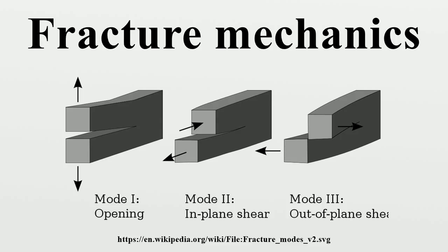The energy release rate for crack growth, or strain energy release rate, may then be calculated as the change in elastic strain energy per unit area of crack growth, where U is the elastic energy of the system and A is the crack length. Either the load P or the displacement u can be kept fixed while evaluating the above expressions.